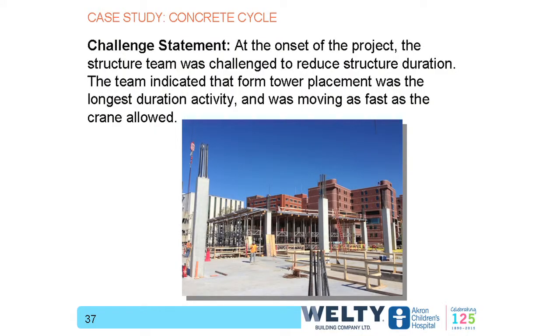The structure is important, but there's not a lot that can happen until we get the building frame and the floors up, and that's when we can really start rolling on a project. So we really wanted to focus on that. We looked at what the building process was going to be for the structure. We ended up going with concrete. We could have used steel. It would have taken less time and it would have been less expensive. After going through the analysis, it was the team's decision that long-term for the hospital, concrete was going to be a better structure. It was going to give them more flexibility and a lower operating and maintenance cost for the building, so we wanted to go with that, but we needed to drive time out of that process.